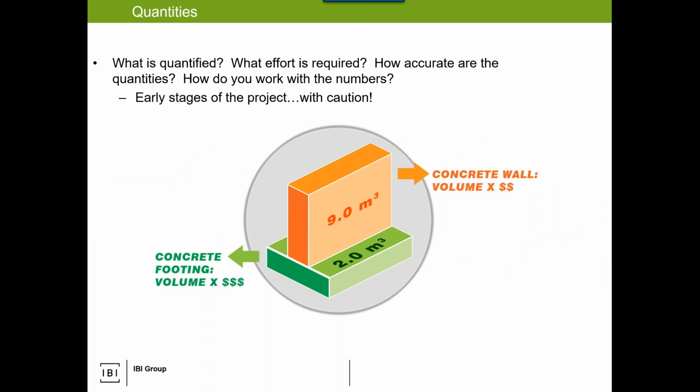Other times we may have the cost estimating BIM use, and as a BIM lead, we're asked to provide quantities. And I've come across this many times. Here's your volume of concrete. The answer: that's not good enough. I need to know what type of concrete. And the reason is the cost of concrete is coupled with the rebar and the formwork, and there are different multipliers for where the concrete is. Is it a slab sitting on grade? Footing versus foundation? Elevated slab?